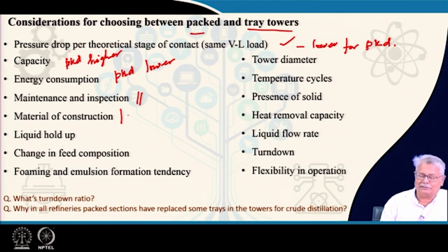It could be graphite or something which is basically non-corroded. So, you have some advantage in case of packed tower, because the packed tower can have non-metallic packings.